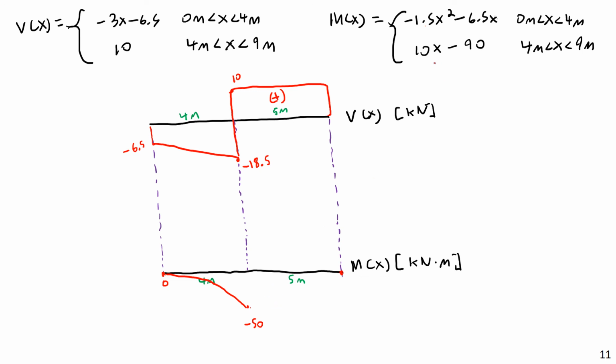So this thing starts out at 0. Let's start again. This starts out at 0 and it's going to end up at 0, and we'll have something like this. And so we actually have negative bending moment throughout. In the first simple example, we had positive bending moment throughout, and in this one, we have negative bending moment throughout.